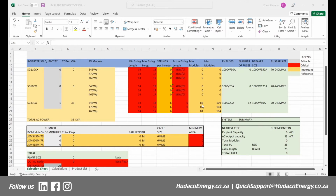It tells you that if you're using 545s, for a 33 kVA inverter, you need between 86 and 109 panels. If you're using 470s, you need between 81 and 104. If it's 465, it's the same because 465 and 470 are very close to each other, so it doesn't really make much difference there. And this is the number of strings per inverter. As we said, it has got 3 MPPTs with 2 inputs per MPPT.